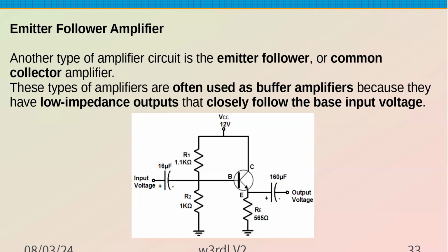But you may have an oscillator. Typically, an oscillator circuit won't have very much power output. If you try to draw much power out of it, you affect the frequency of it, even to the point where it will stop oscillating. So you put something like this in between, so you isolate that oscillator from the other part of the circuit, and you can have a higher power output at a lower impedance.